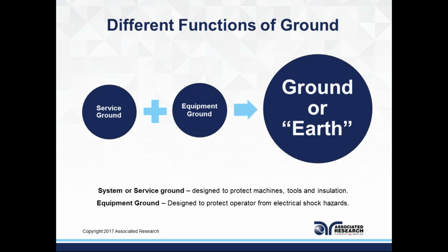Again, defining a service ground, this is a ground that's meant to protect machinery, transformers, motors, to protect the instrument and the installation around the instrument. It is not meant to protect any of the operators that may use the product, or any end user that is using the actual product. The service ground is also protecting the house from catching fire in the event that fault current has to go through the wires. The service ground takes care of the charge.